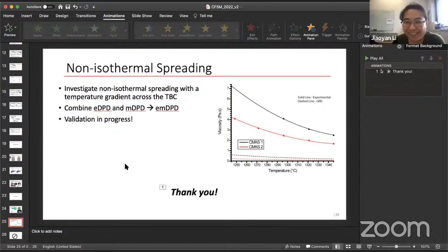One trick that I've seen in the literature for liquid to vapor phase is that they just delete particles. Based on the latent heat, if a particle becomes vapor, they just delete it from the system. But if you do the liquid to vapor transition, the system will absorb a lot of heat, so if you just delete the particle, you did not solve the problem. You have to consider how the energy is changing in the system.